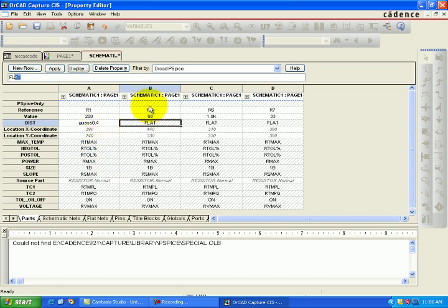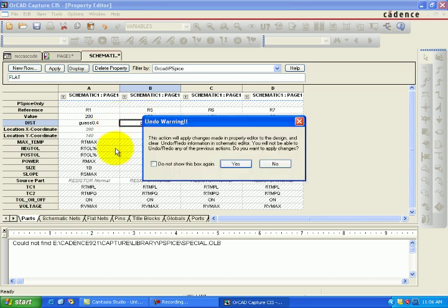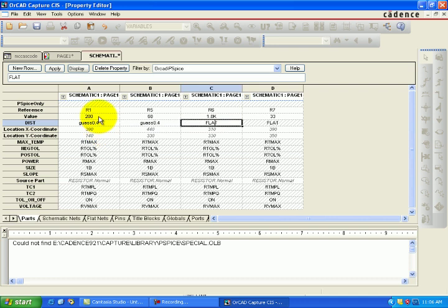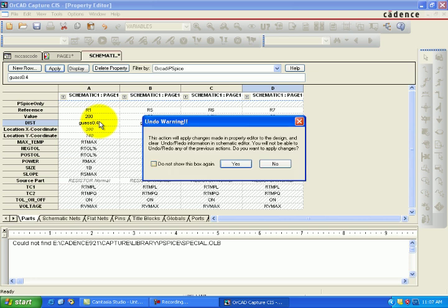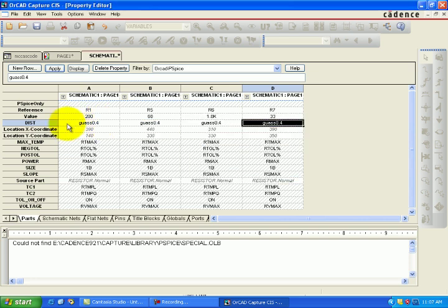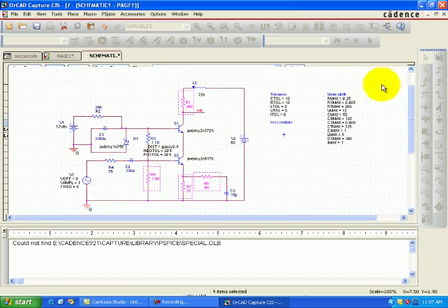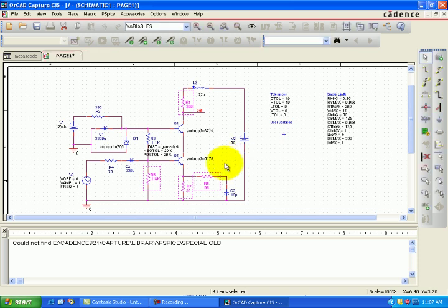The distribution controls how the Monte Carlo will vary the parameter. We can vary it as a flat or a Gauss or a bimodal. So this is how we want to distribute the properties for the Monte Carlo analysis. We have to change it for all to Gauss of 0.4 resistance values, and give a positive and a negative tolerance, like 10%, 20%, whichever. Apply.